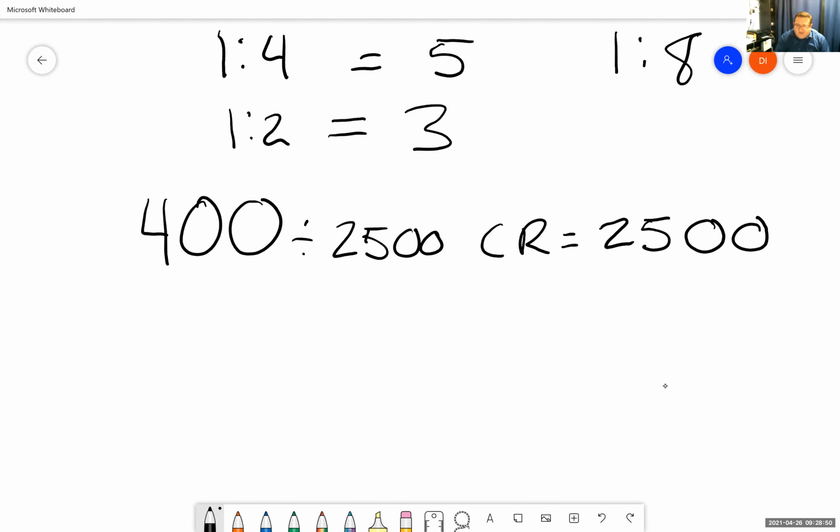That's 0.16. Yep. Okay. So 0.16 of a gallon would be enough to put 1 coat on that floor. We did 2 coats, so we'll multiply that by the number of coats. First of all, we got 0.16, and we multiply it times the 2 coats we did.